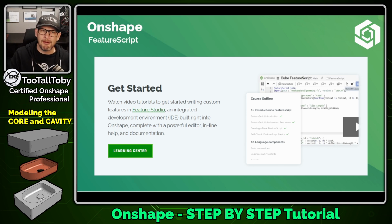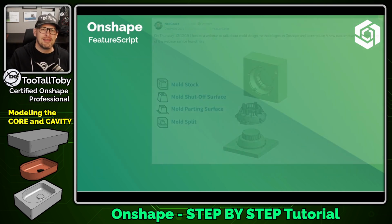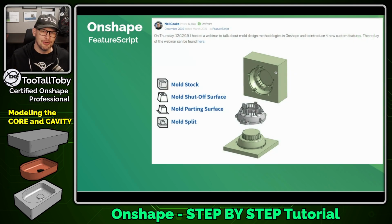The thing that's really cool about FeatureScripts is that somebody else could create these FeatureScripts and then share them with you and with the entire Onshape community. And these are typically found in the Onshape forum. And this post that I'm showing a screenshot of here comes from Neil Cook. I'll include a link to this post down below in the description, but you can see here that there are mold tools available for all Onshape users, like mold stock, creating the shutoff surfaces, creating the parting surfaces, and then doing the mold split. So these tools are absolutely available to everyone, and this will automate the process.